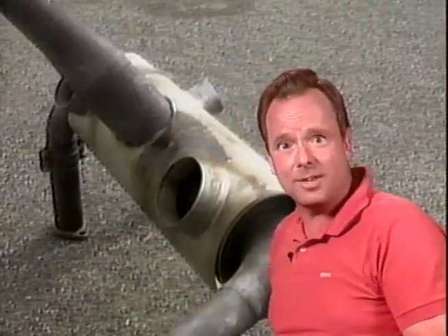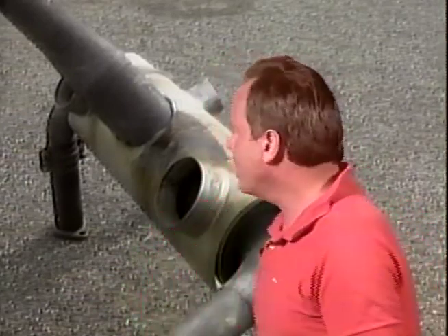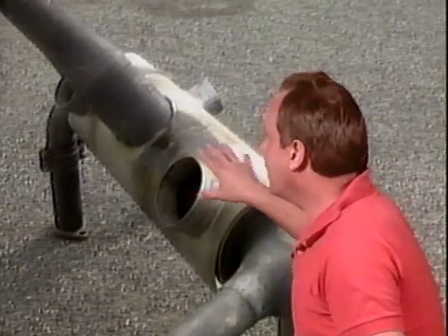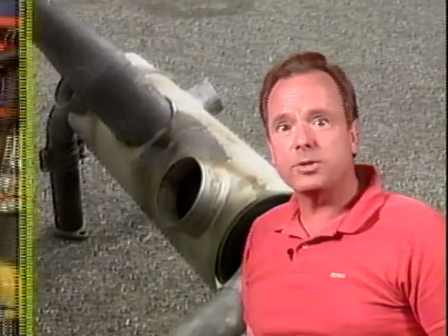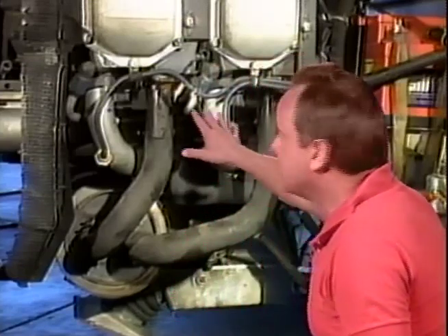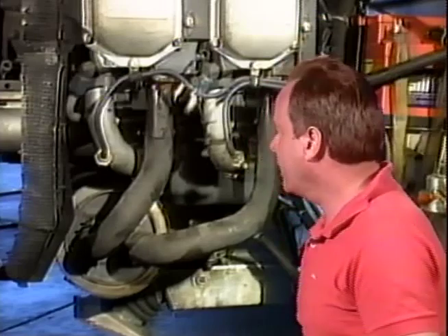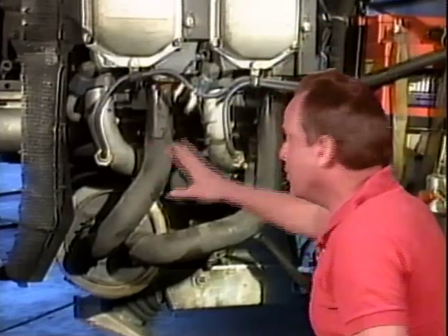Here's another one. An aircraft that utilizes an exhaust heat exchanger as the source of cabin heat, that's it, should have the exhaust system inspected with the heater air shroud removed. So they're saying take off this shroud every now and then and look at the exhaust system itself. All right, reciprocating exhaust system leaks are a bad thing. And so how do you tell when you have an exhaust system leak? Well, you might see soot. That's a question on a test. You can detect exhaust leaks by signs of exhaust soot inside the cowling and on adjacent components. So if you see soot around here, it tells you might have an exhaust system leak.